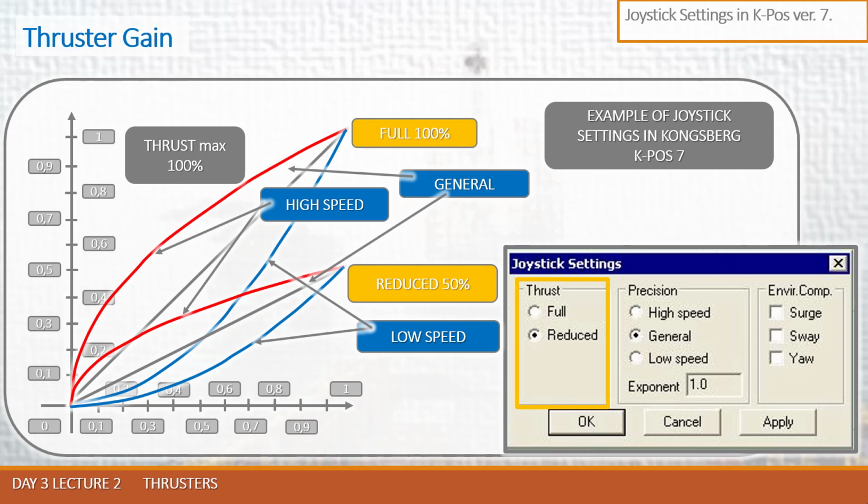Operational experience plays a large part in determining the optimum gain level, but the following general points should also be noted. High gain provides the quickest vessel response, the most accurate maneuvering and the smallest position window. Medium gain provides a slower vessel response than high gain. Low gain provides the slowest vessel response and the largest position window. Remember that, please.